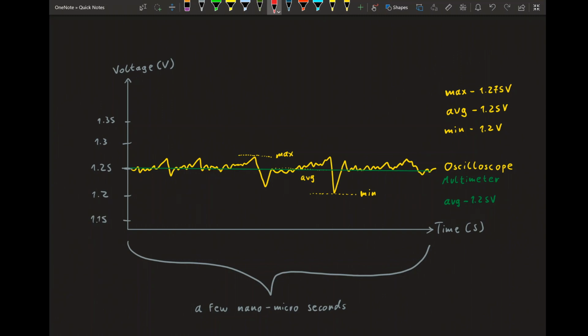And just to make sure that we're actually running 1.25 volts, we take a multimeter, the line that's in green right here, and we check at a capacitor that's reasonably close to the CPU, or somehow we manage to. Sometimes you can probe the die sense circuit, or let's just say we look at the die sense voltage in HWiNFO, and we make sure that our die sense is actually 1.25 volts. So yeah, we're gonna see a nice static 1.25 volts. Everything is fine. Our CPU runs 5 gigahertz, and that is good and well.